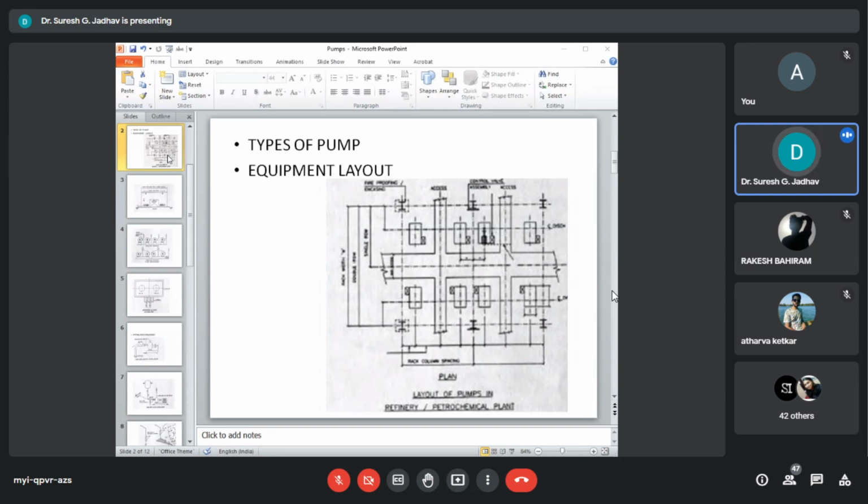A number of pumps should be lined up and aesthetically well arranged. Pumps are arranged under the pipe rack in a refinery or an outdoor process plant, keeping the motor end towards the access space and suction discharge faces towards the process vessels. A single pump should have access all around, a minimum of 900 millimeters.